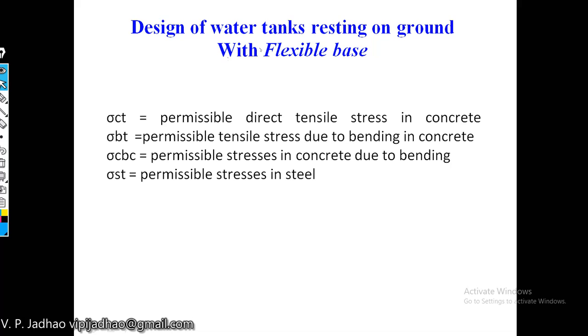These are some terms which will come into contact while designing this type of water tanks. The first one is sigma ct, that is the permissible direct tensile stress in concrete. Sigma bt is the permissible tensile stress due to bending in concrete.